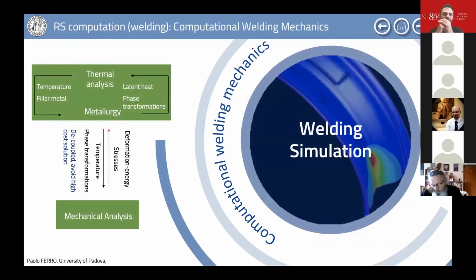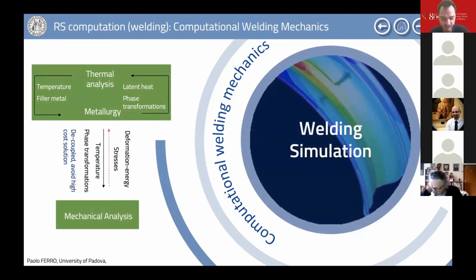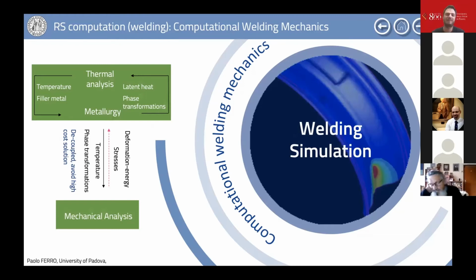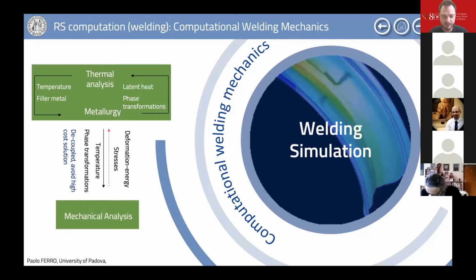About the assessment of residual stress, we have another possibility: the possibility to use numerical modeling. This is one of my principal topics. And of course, using welding simulation, we are able to have knowledge of the residual stress over all the components, in all the geometry of the component, not only in single parts, as we can operate using experimental techniques.